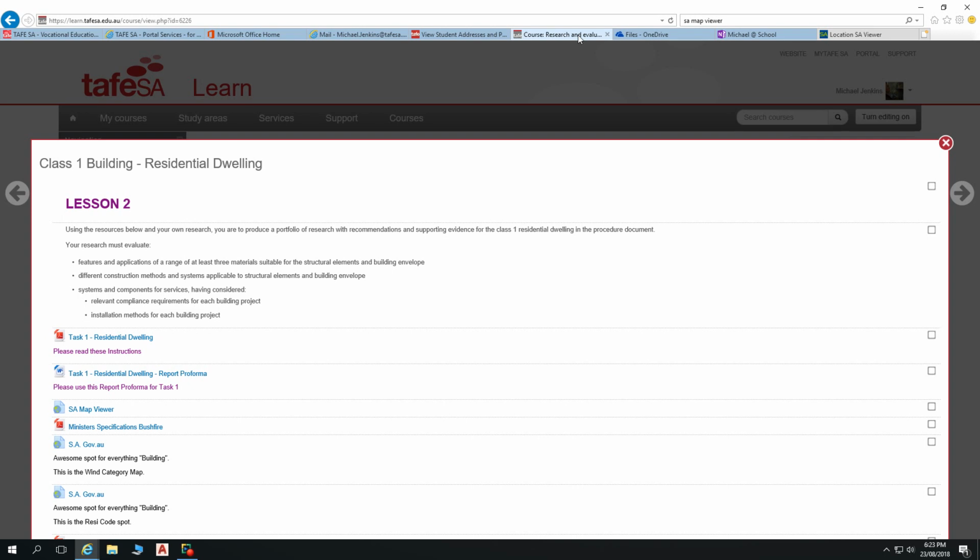You could talk about the weights of, say, cladding forms and so on, and their impact upon footings. We're not going to use a suspended timber floor on stumps with double brick cladding walls, for example. If we're going for a lightweight flooring system, we're going to have a lightweight building above it. So some of our heavier cladding and construction approaches are not going to be suitable for lighter weight footing systems.